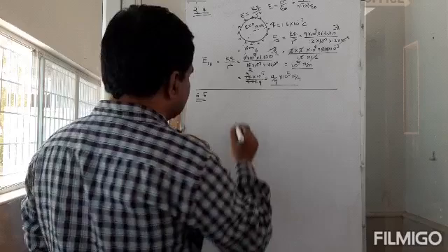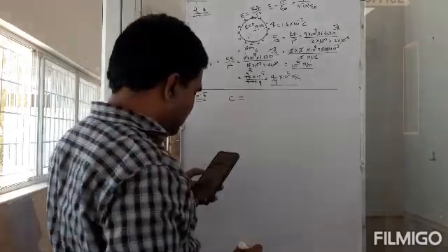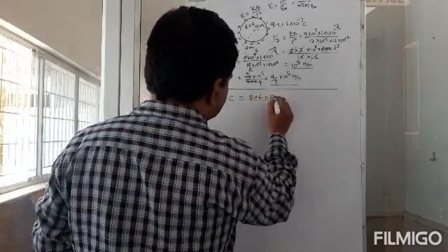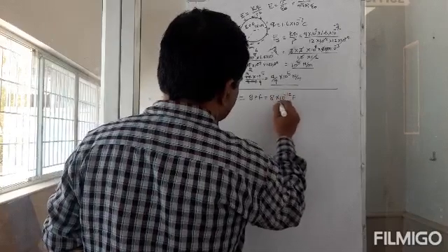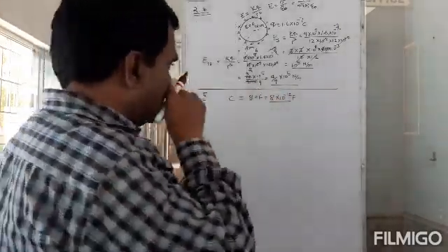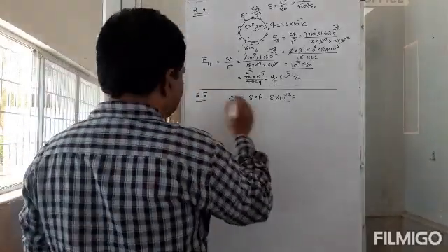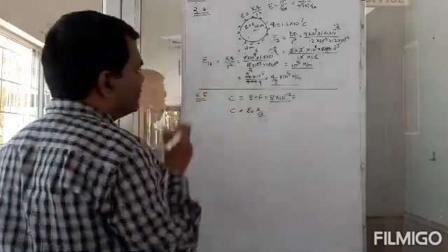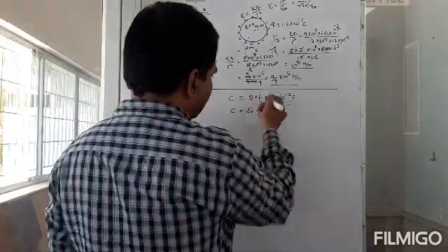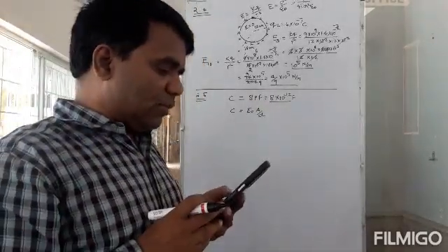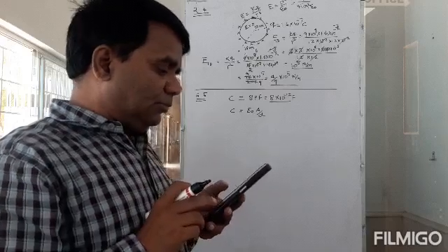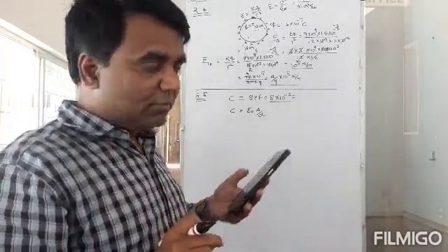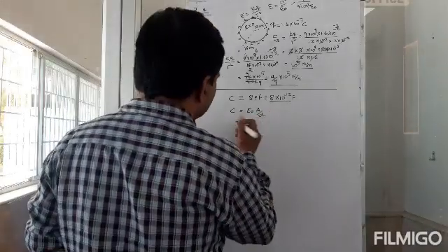2.5. You already have a capacitor, a parallel plate capacitor, and its value is 8 picofarad. 8 picofarad is equal to 8 into 10 power minus 12 farads. Okay. So what do we know now? For a parallel plate capacitor, C is actually epsilon naught A by D. Okay. So this is equal to this value. So what are they doing now? Now they are reducing the distance of separation between the plates by half. So what is the new capacitance for this?